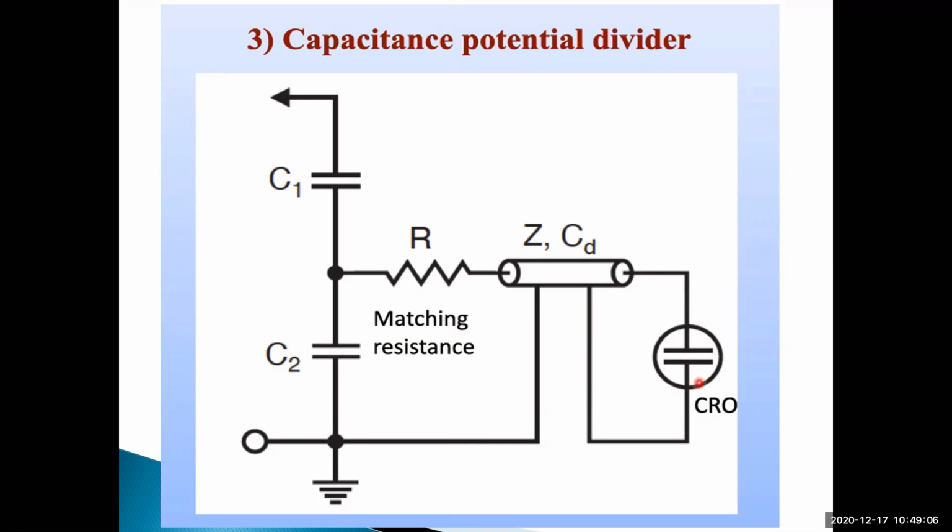It is acting just like a voltmeter. That's why, in a laboratory, you connect the CRO in parallel to the resistor only, or in parallel to the capacitor only, not in series. The CRO is connected in parallel to the element, not in series.